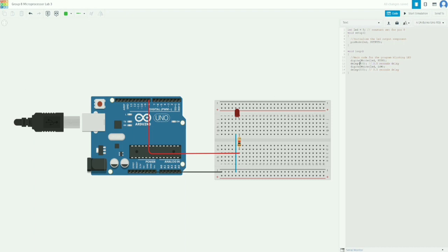As you can see, we have the 500. This is because we are using milliseconds for the delay. In this case, it causes a delay of 500 milliseconds, or when converted to seconds, 0.5 seconds. We also have digitalWrite LED, LOW, which is low voltage, turning the LED connected to it off, and another 500 millisecond delay for the off, which creates a total cycle time of 1 second, 500 milliseconds on and 500 milliseconds off, as per our objective.